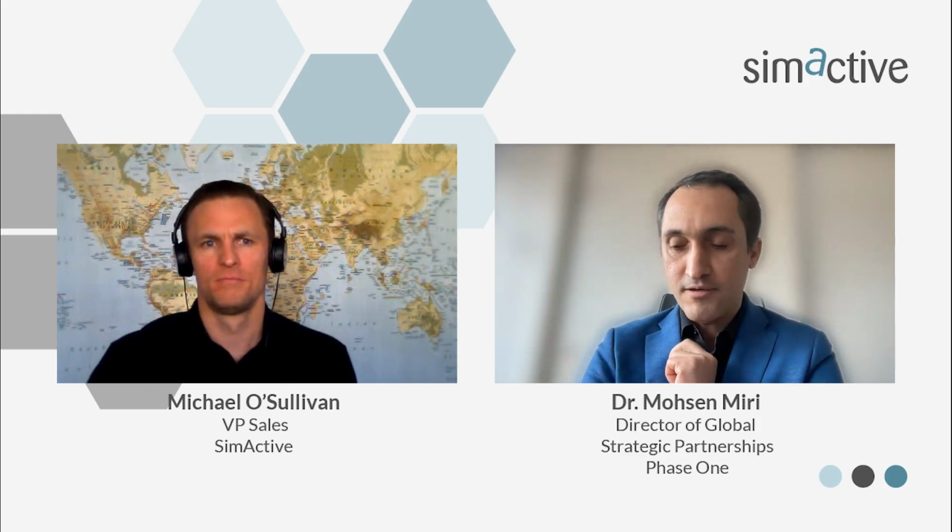I come out of the imagery, let's say, photogrammetry. If we want to, for example, extract or capture the ground under the canopy of very, very dense forest, obviously we should use a LiDAR, right? Because in dense forest, specifically in summer, we cannot reach the ground, right? So choosing the right sensor is very, very important, right? Different project, different objects that we would like to get, and the right sensor.